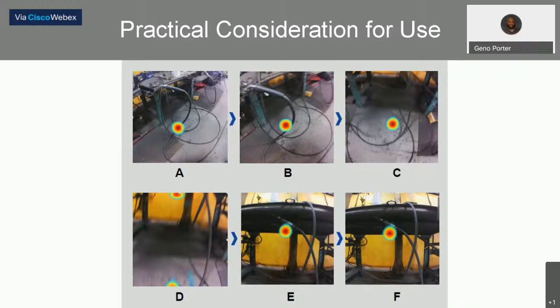So how can you tell whether something's a reflection or if it is the source? Great question. This is what this pictorial graph is showing us. Picture A shows someone holding an ii900 and pointing it towards the ground. The technician is going to have enough experience to scratch their head and say, hey, is there air coming from the ground, or is this a reflection? But if you don't know, here's a trick. Move your location, change your position. And if that spot on your ii900 moves on the screen, then it's not the true source. That means it's a reflection.